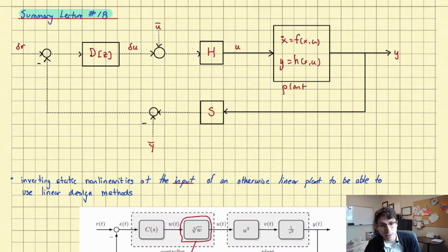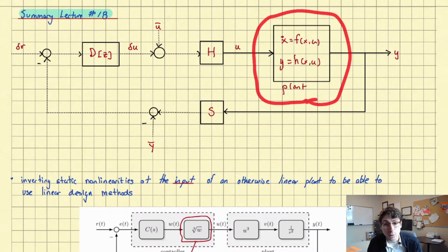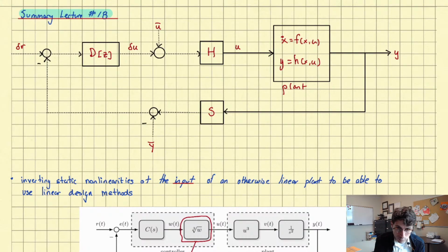One of the things to take away from last class is this: what is this picture showing you? You should understand what this picture is saying. The basic idea, again, is that you have to introduce these biases so that you are close to the operating condition. And if you go to simulate this system, you want it to work reasonably well, so your nonlinear system that you're controlling should be initialized either at the equilibrium or nearby. If it's not, then you wouldn't expect the controller to work that well. So keep that in mind when you're simulating or testing in an experiment.